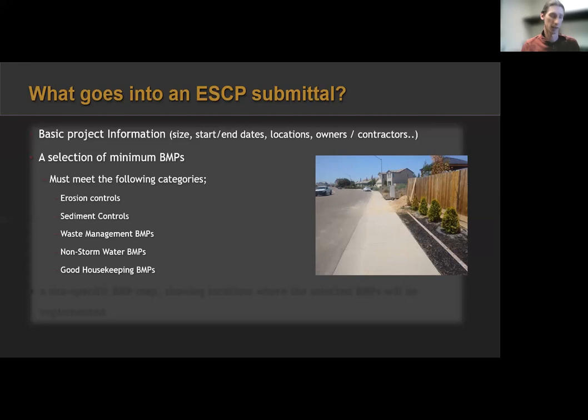And how they address that is usually we will give them in our erosion sediment control plan a list of BMPs to meet that they can use. They might have some descriptions of what those BMPs do if they are not familiar with these, but we try to use the industry standards. We try to use CASQA BMP cut sheets, which we say, hey, you can go and look those up and look for references of cut sheets. You can use the Caltrans cut sheets if you want to. Look up these references and implement them on your project if you don't know what they are.